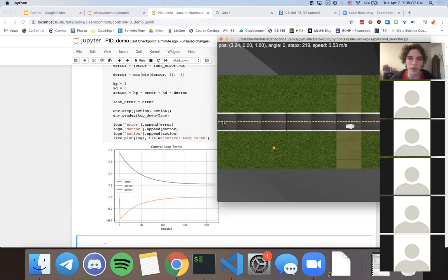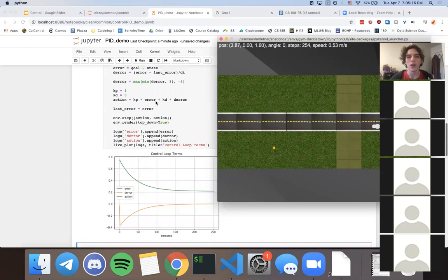And this is a common issue in many systems. It wasn't apparent in our last system, but if we added friction or stuff like that, it might have changed. So we need to add something else here. What happens here is if we're at 0.53 constantly, then our error has reached a constant number. It's about 0.2, which means our action is roughly constant at like 0.2 throttle. But 0.2 throttle might correspond to this velocity. And we need a higher number to reach the higher velocity. So whatever we do, just using something like error and d-error isn't going to be enough in a system where a constant error won't lead to change.